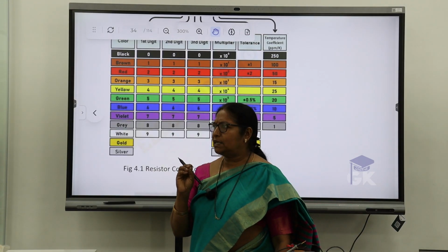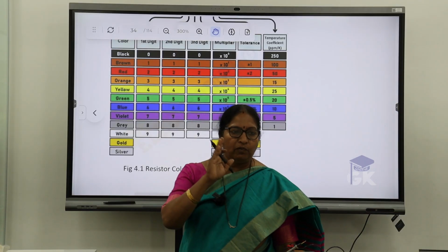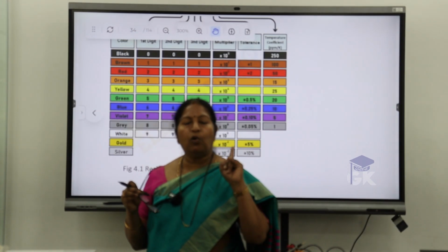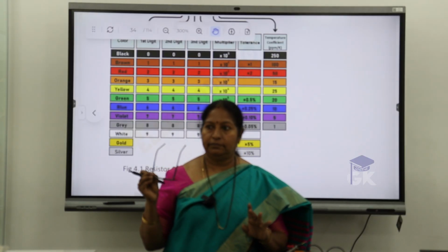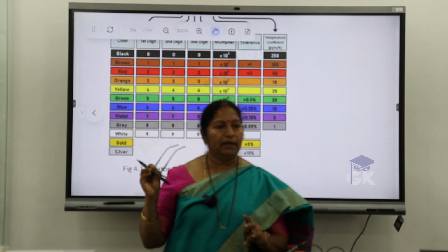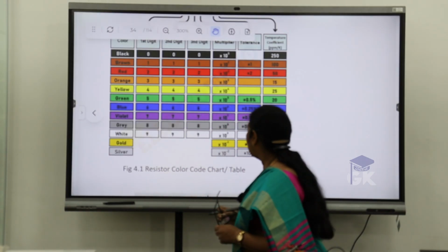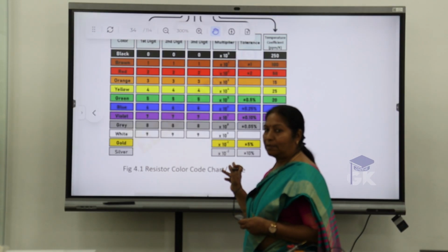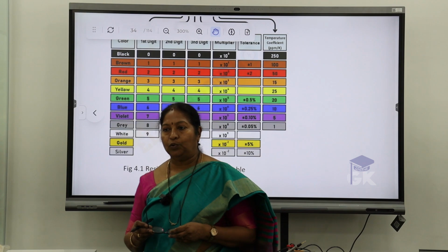What is that 5%, 10%, what does it mean? Suppose, let me say, write down all your values in yours. How many of you have got a gold color? Gold. Okay. Who has silver? No one. Okay, gold color. So gold color, what is the tolerance? Plus or minus 5. See, that's what you just observed very clearly. Plus or minus 5%, write down the value.